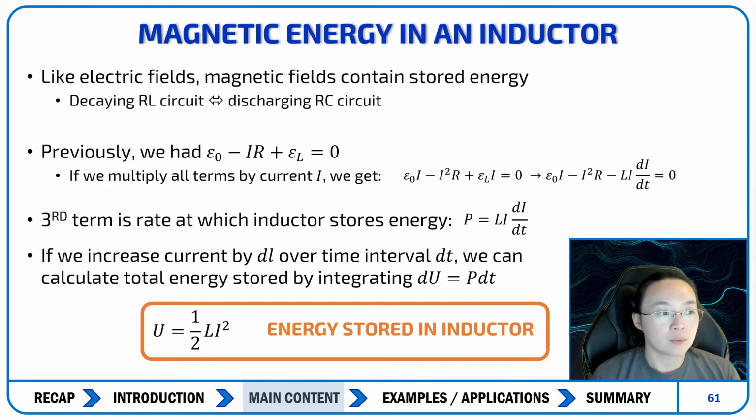So what is magnetic energy in an inductor? Like electric fields, magnetic fields will contain stored energy. A decaying RL circuit is basically synonymous to a discharging RC circuit, so we can make those connections there. Previously, we had this loop equation. If we multiply all the terms by a current I, we get this equation over here.